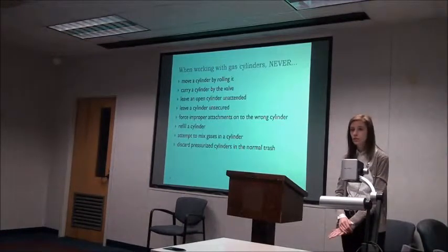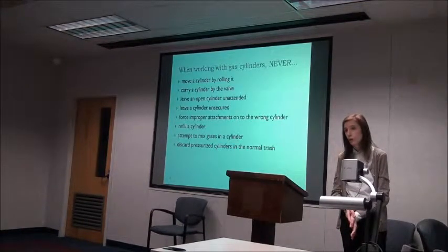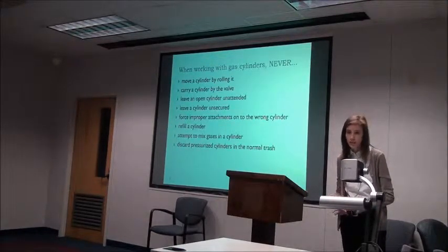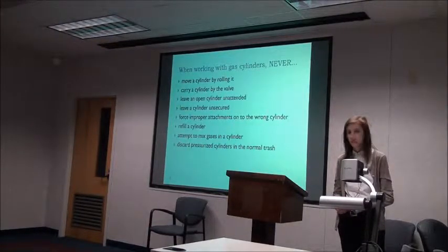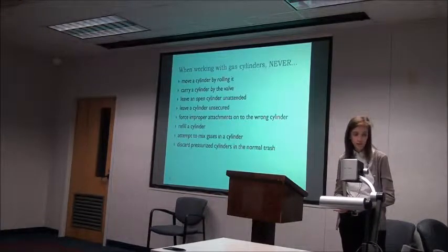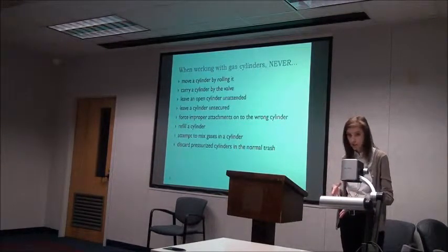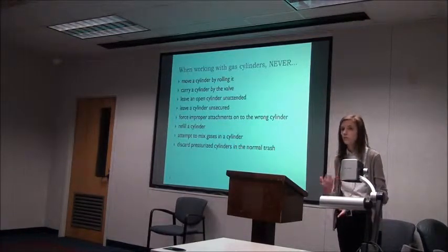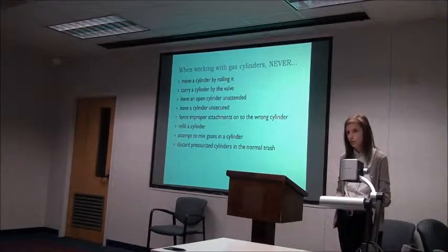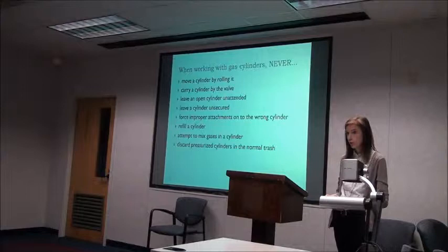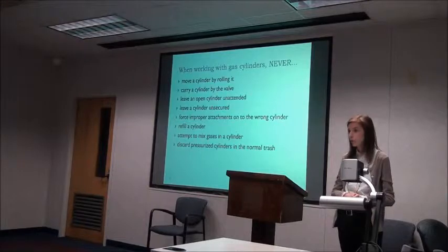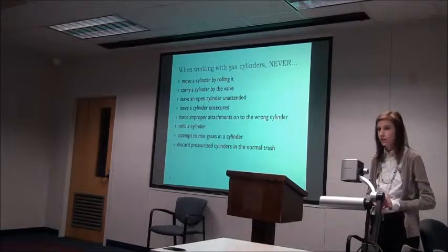When working with gas cylinders, never attempt to move a cylinder by rolling it, never carry a cylinder by the valve, never leave an open cylinder unattended, never leave a cylinder unsecured, never force improper attachments on the wrong cylinder, never refill a cylinder or attempt to mix gases within a cylinder, and never discard a pressurized cylinder in the regular wastebasket. Always notify your instructor or ask your instructor where to properly dispose of the cylinder once it's used. This information was obtained from the University of Wisconsin-Milwaukee, from their health and safety website.